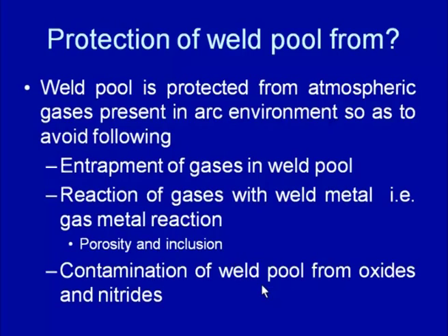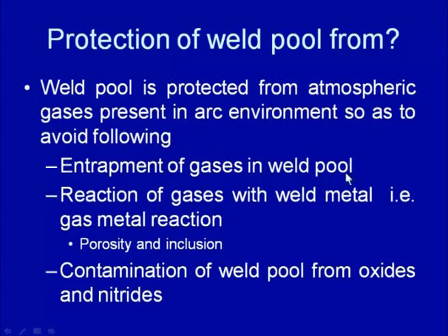So, if atmospheric gas is present in the arc environment, it can lead to entrapment, resulting in porosity and inclusions, and further these gases reacting with the weld metal can form a variety of oxides and nitrides, which can lead to undesirable microconstituents in the weld pool.